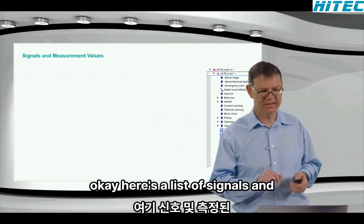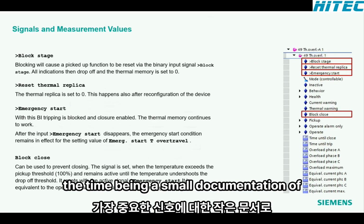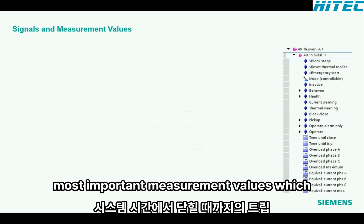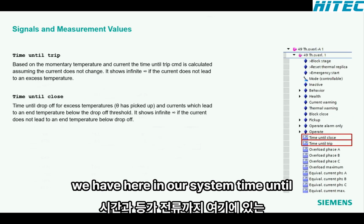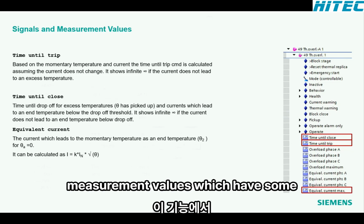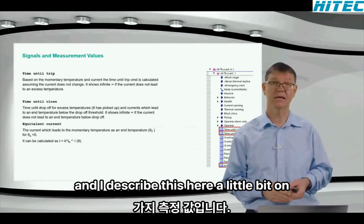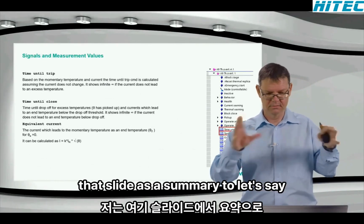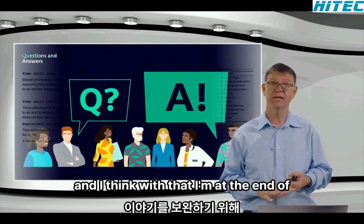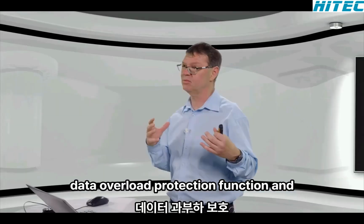Here's a list of signals and measured values. I just put it here for the time being, a small documentation of the most important signals and also the most important measurement values which we have in our system: time until trip, time until close, and the equivalent current, basically. These are 3 measurement values which have a certain meaning in this function, and I described this on that slide as a summary of what we have as settings, to complement the whole story. And I think with that, I'm at the end of the stator overload protection function and the thermal model.